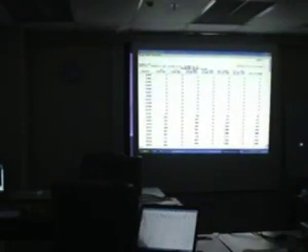So again, it's by every 1 meter. And for the cut area, fill area, cut volume, fill volume, cumulative volume for cut and fill, and your mass ordinate. Mass ordinate is basically cut minus fill.